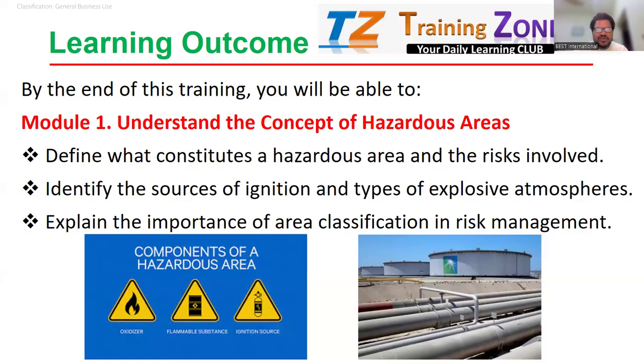If it is a confined space, and any place which is not designed for human occupancy, we all know is a confined space. So if you're going inside, before first entry, again, gas testing is mandatory. When you are coming back, you don't work in a confined space without a standby man. You don't work without a confined space entry supervisor. You also get help from your safety leadership. They are the ones guiding you, supporting you, and making sure you are working in a safer environment.